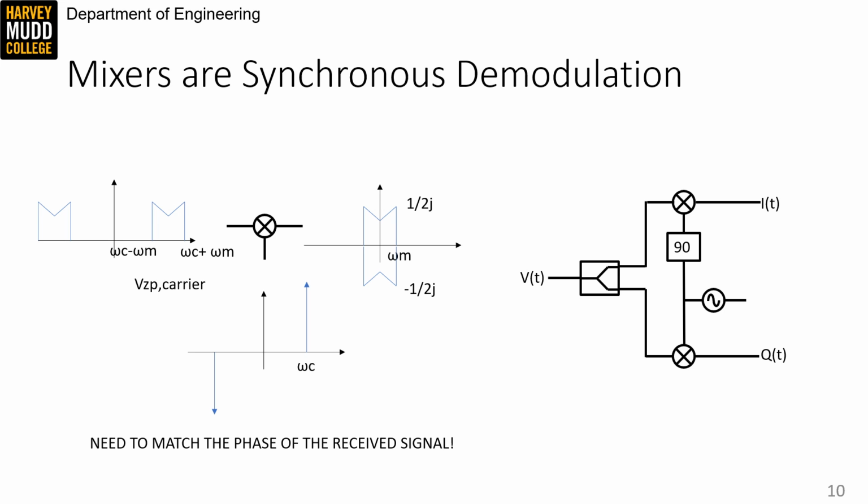We already know that mixers allow us to translate the frequency of a signal, so can't we just mix high frequency signals down to low frequencies and call this finished? Unfortunately, no. That's because we depend on the local oscillator being in phase with our incident signal in order to mix the incident signal to baseband. I've shown an example of that not happening correctly on this slide.